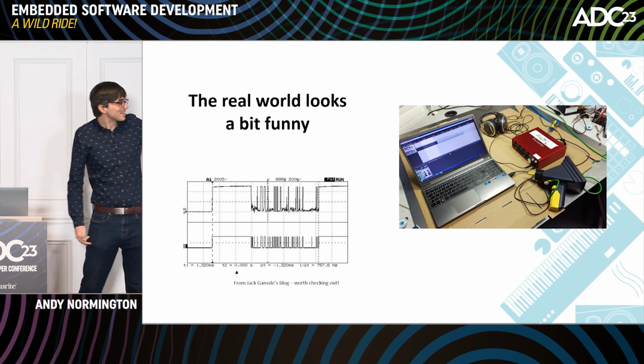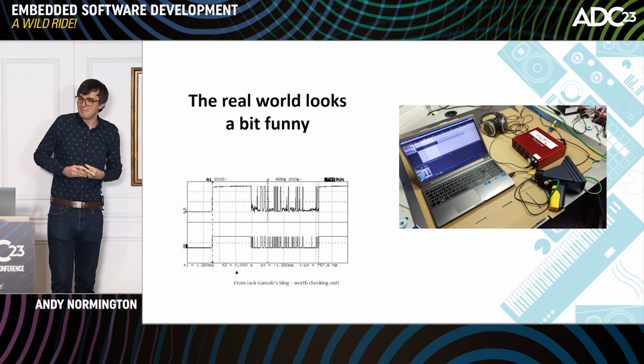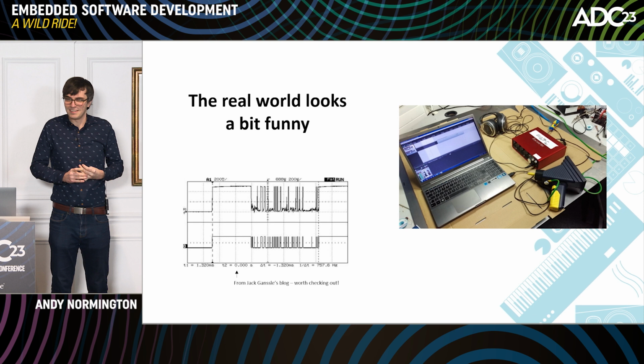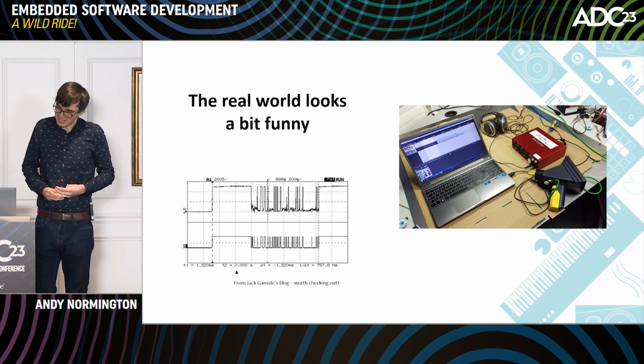That might be spending some time in that kind of no man's land between TTL levels. We have to find a way of differentiating between quick button presses and absolute mess coming from a switch like this, so we don't get false presses.